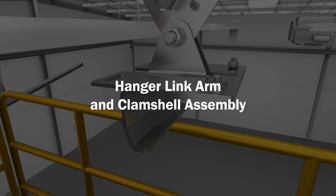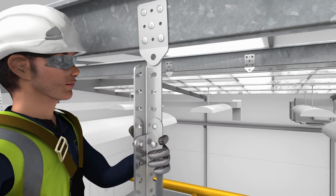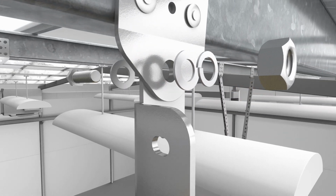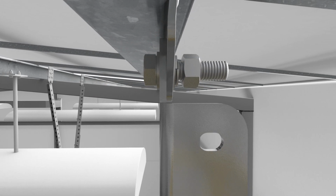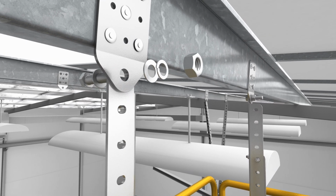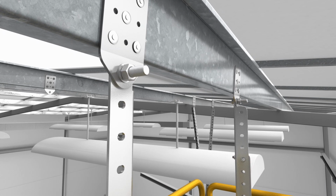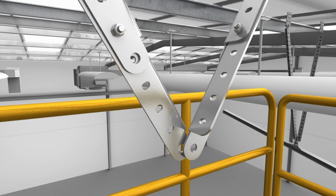Hanger link arm and clamshell assembly. Selecting the appropriate hanger link arm assemblies relative to their position as prescribed in the system design specification, loosely secure the hanger link arms using M16 50mm bolt assemblies. Bring the hanger link arm assemblies together to form a V.